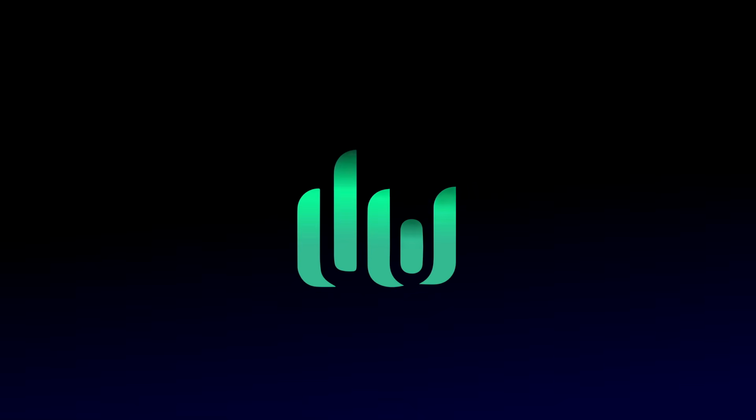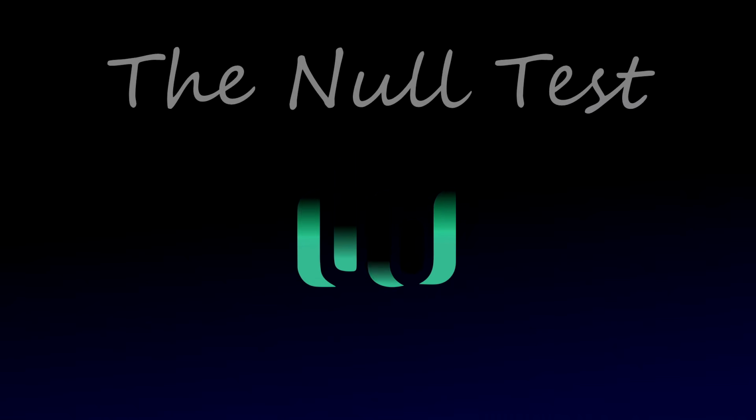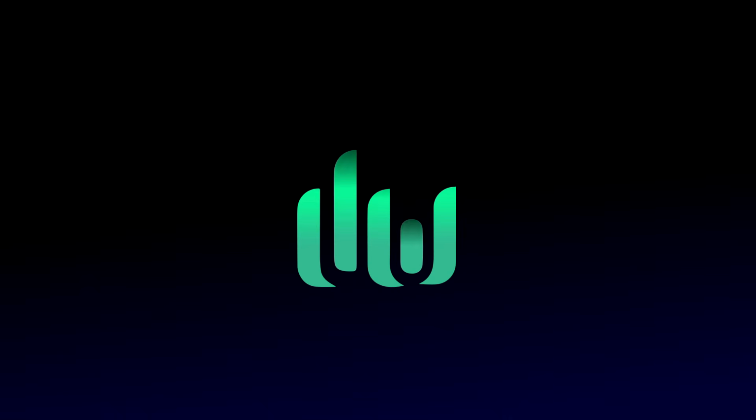I'm going to start with the gold standard of audio tests, the Null Test. This is one of the few tests that can give us a definitive yes or no answer. But it's an answer to the question, are there any differences between these audio signals? It doesn't address the follow-up question, are those differences actually audible?